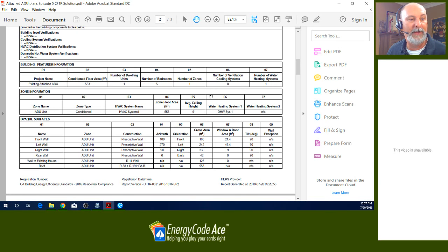Now I do like to clarify that the Energy Commission's recommendation is that indoor air quality fans be installed, but technically, according to the code, it does not trigger it. So it's always a good recommendation, from the energy consultant standpoint, to recommend that they address indoor air quality, because it is its own dwelling unit. It is technically not in communication with that existing house that may already have an exhaust fan. So great recommendation.